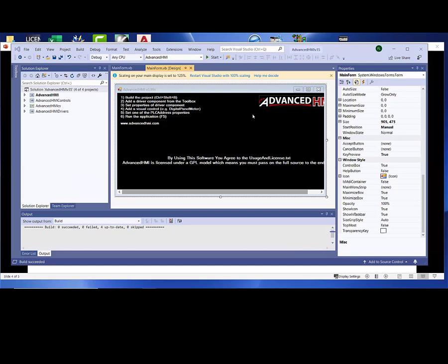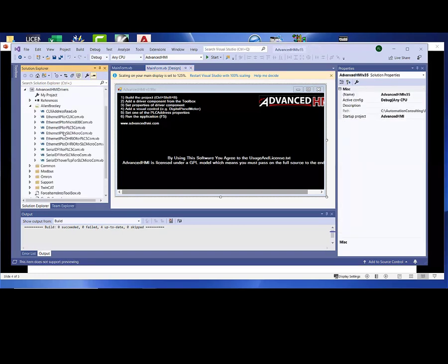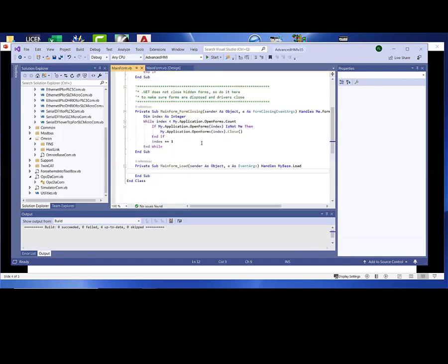So what you do is first install Visual Studio, and they'll talk about which version you need. Then you go and download Advanced HMI. What Advanced HMI is, it does have some nice controls that are easier than Visual Studio, like graphical push buttons, like the ones I showed you. And it also has all the drivers. So Advanced HMI drivers, what you're doing is plugging all of these in, right? Here's the Allen Bradley drivers. Here's the Omron drivers. You're plugging all these into this, and then you're dragging objects from the controls in the toolbox, and then you're editing in Visual Studio.